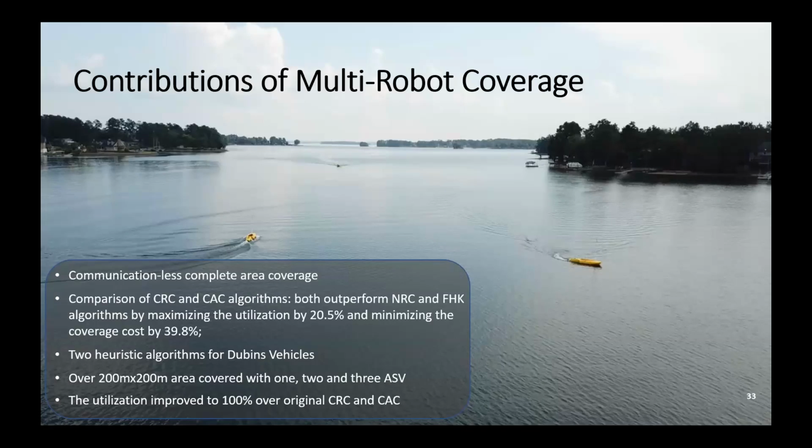But if you have a vehicle that has to travel some distance in order to turn its heading, that's called non-holonomic, or a vehicle with a Dubins constraint. So there is a minimum turning radius that the vehicle is going to take in order to perform the rotation. So that's the particular curvature of Dubins.